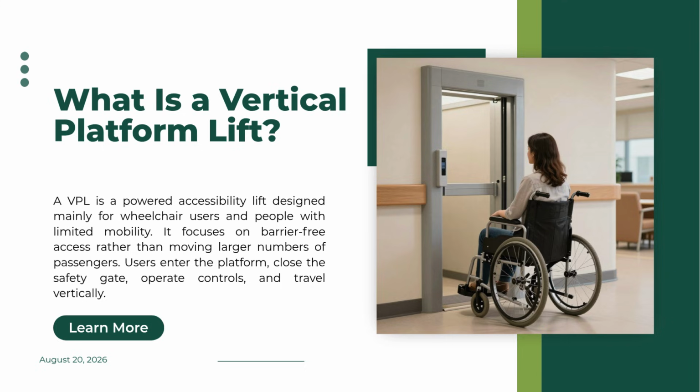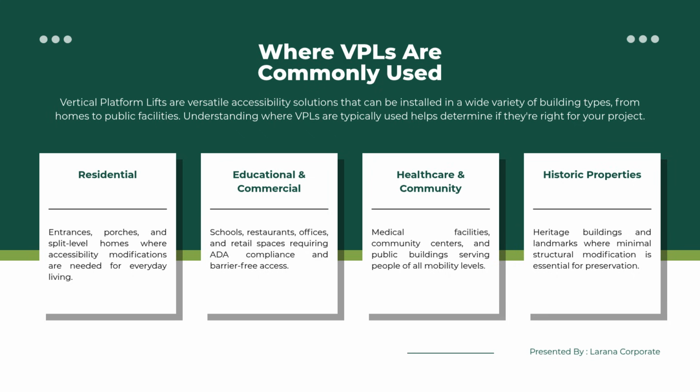2. What if shaft space is limited? Limited shaft space is one of the most common retrofit challenges. A conventional elevator shaft needs room not only for the cabin, but also for guide rails, doors, structural supports, equipment, and maintenance access. If the available space is very small, possible solutions may include compact elevator shafts, customized cabin dimensions, alternative door configurations, or machine room-less systems.